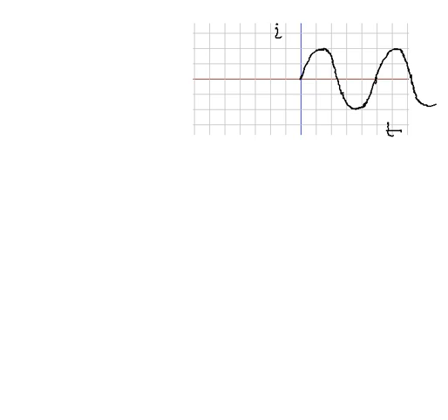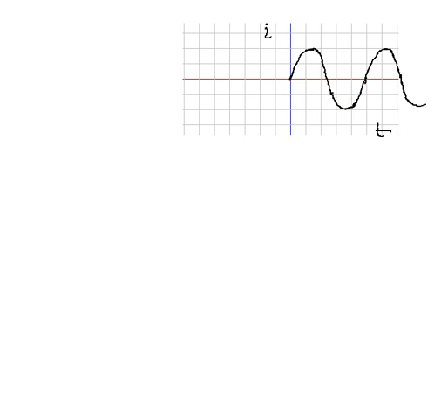So if you look at this graph, then current is positive for some time, negative for some time, positive for some time, negative for some time. It is alternating current. But it also has one more thing. Its magnitude is changing as well. It is 0, then it rises, rises, rises, attains its maximum value, then it falls, falls, falls, becomes 0. After this point, it changes its direction. Then it rises in magnitude in the opposite direction, attains maximum value in magnitude at this point, and then the story keeps on repeating itself.